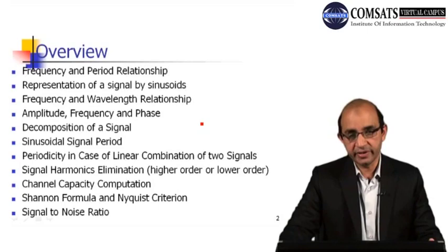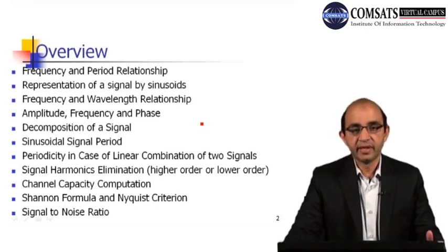For example, if F is the fundamental frequency, then we can have different components that are actually integer multiples of the fundamental frequency F. Normally what we do is take the first few harmonics and ignore the rest of the harmonics, as most of the energy of the signal is contained within those first few harmonics.